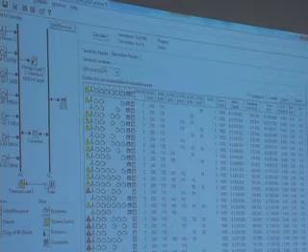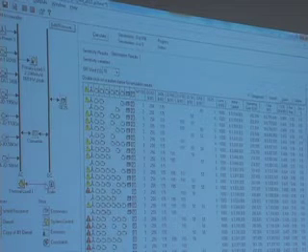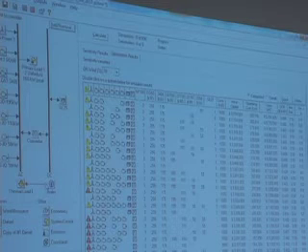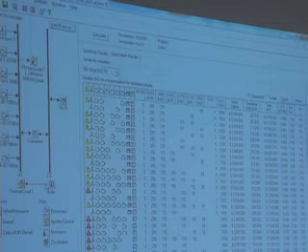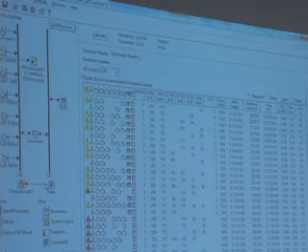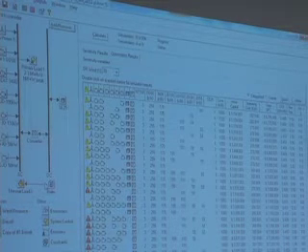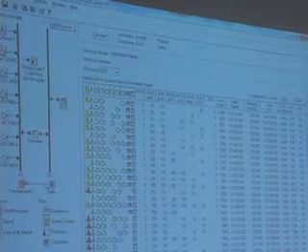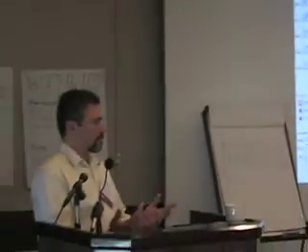It always assumes that there's a boiler. Homer doesn't allow you to have unserved thermal load. It puts in a boiler and makes sure the boiler is big enough. It assumes that you can meet your thermal load, but it uses the boiler efficiency and fuel to calculate the value of the electricity that's displacing the boiler fuel.